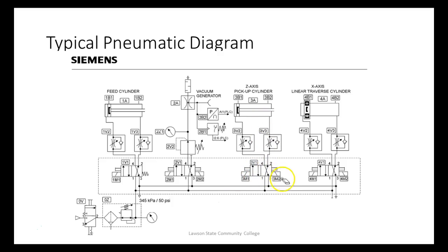And these are basically the same. So this would be a 2, this would be a 4 two-way valve. So we start off with the number of ways, right? Then we put a slash, we put the number of positions, then we say way. Now how they came up with that, I don't know, but it sounds cool. Double solenoid operated, manual override, right? Everybody okay with that one?